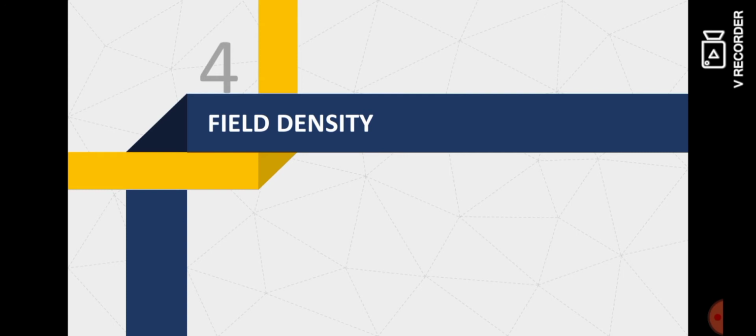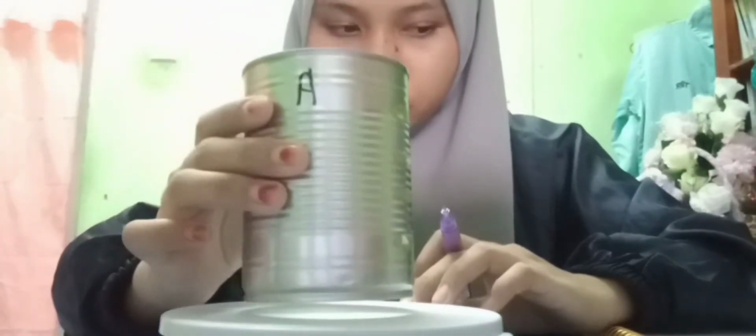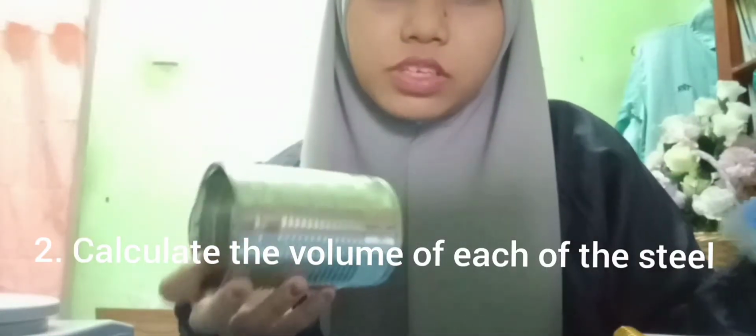Field density. Now I will show you the video of this experiment. This is first the steel container. I use three steel containers of similar size. Next, weighing balance. After that is the mallet. Other than that is the ruler. First step is to weigh the steel container. Next, calculate the volume of each of the steel containers.